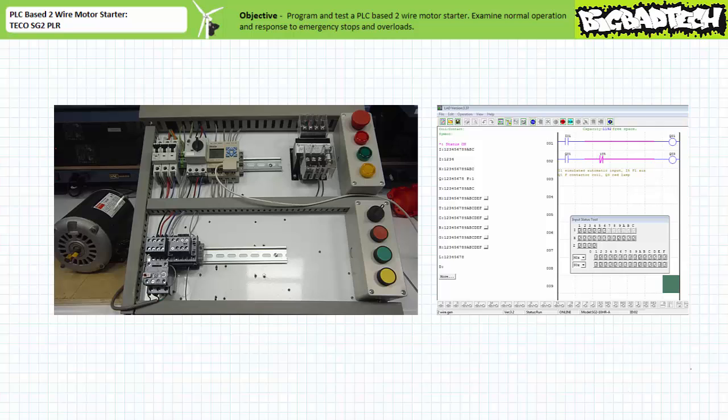While in operation, opening the estop directly depowers both the field input and output devices without reliance upon any programmed instructions to do so. The F contactor coil is de-energized, the F primary contacts open, and the motor turns off. If input I1 is in the closed position when the estop is reset, the F contactor coil is immediately re-energized, the F primary contacts close, and the motor turns on.